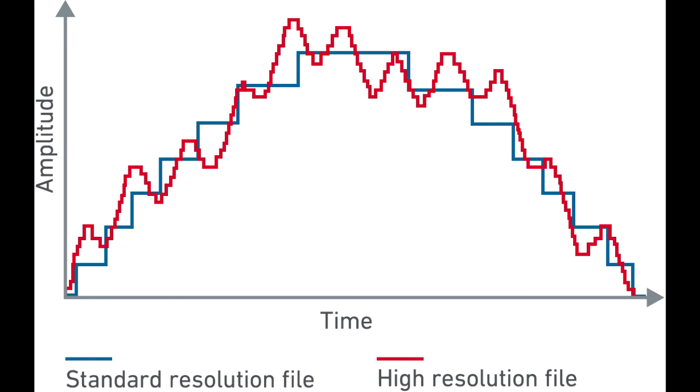Resolution, range, and sample rate are important because resolution allows for a complete look at the data being examined. As can be seen from the picture, with lower resolution, the data collected could not completely acquire all the data points for the sine wave. It only goes to the limit in which the resolution is set. From that, knowing the range of the measurement, in which the maximum and the minimum value are to be set, can help define the resolution. That is why range is very important for the experimental data.